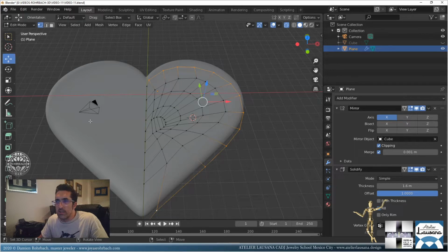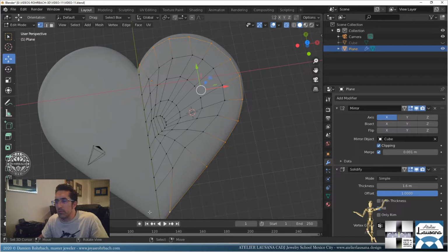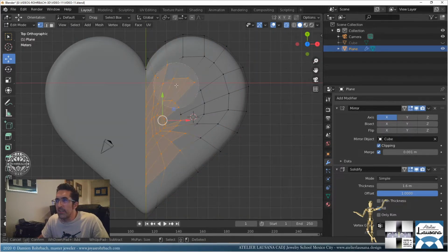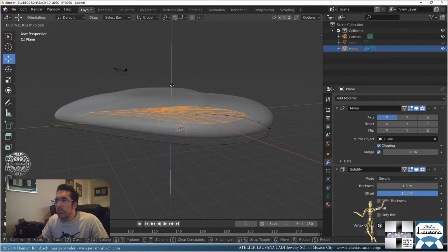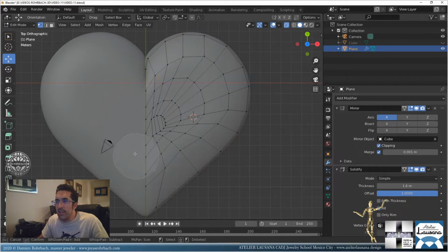Let's start moving this. Or better, let's start from the inside out. Inside. So C key, select these guys, and let's go up. Now every time we're going to select another level, Alt A, C. So every time I take one step back.